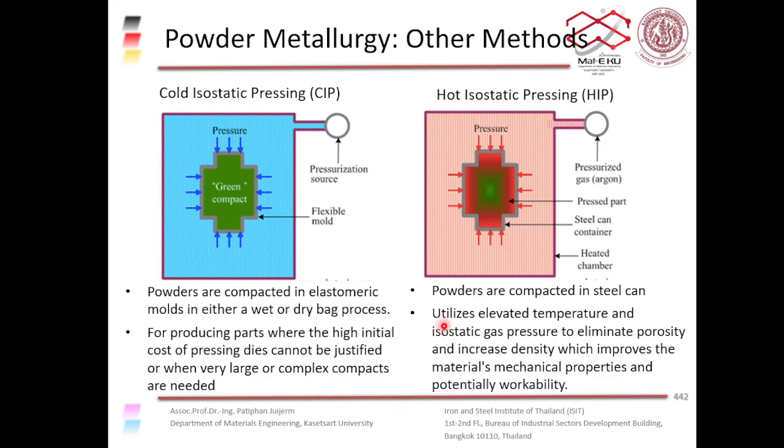We utilize the high temperature and isostatic gas pressure to sinter the workpiece, to eliminate the pores or the empty space inside, to increase the density, and that will increase the mechanical properties of the material, and will also increase the workability as well.